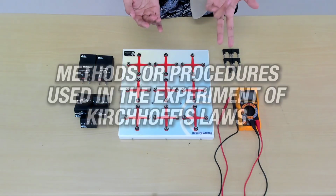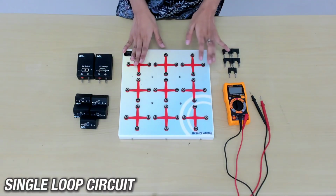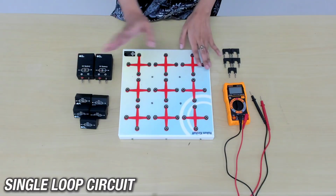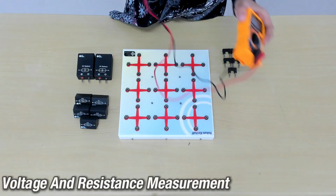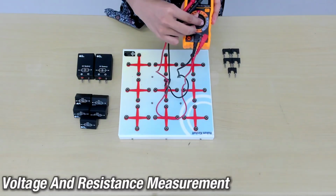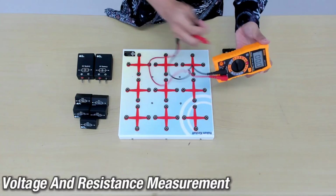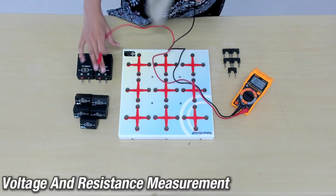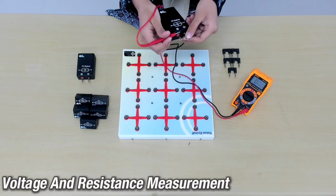Okay, there are 2 variations used in Kirchhoff's law, namely the single loop circuit and the double loop circuit. Okay, for the single loop circuit, initially measure the voltage of the battery as well as each resistor. Okay, to measure the voltage using the multimeter is by turning the dial to the DC voltage reading. Then connecting the probes to the battery terminal.